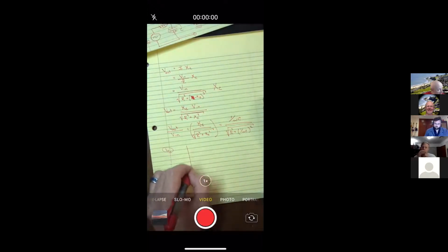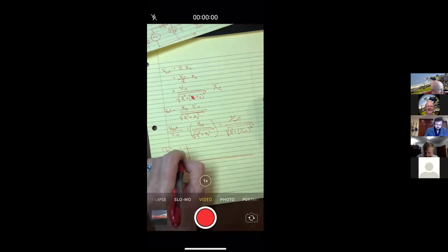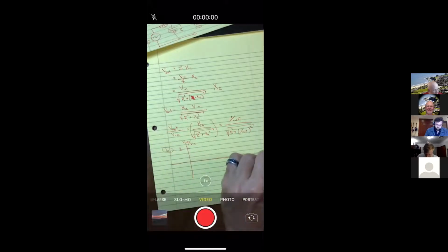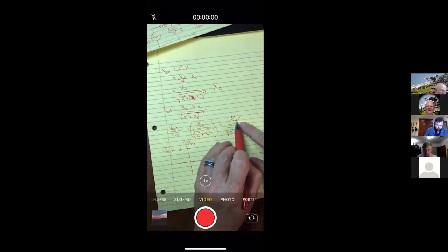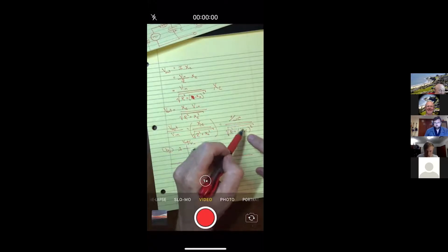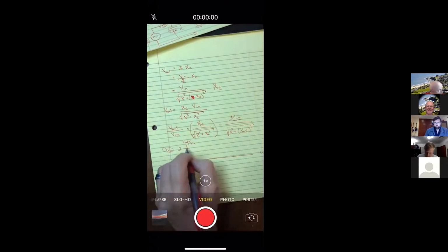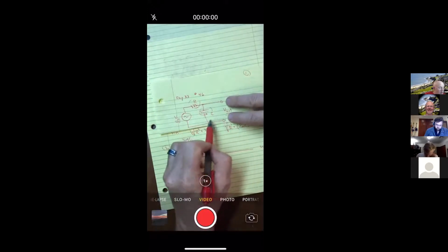So if I was making a plot here, and maybe I'll put the number 1 here, and on the vertical axis put the output voltage compared to the input for different frequencies. Watch what would happen at low frequencies. See, at low frequencies, this 1 over a small number is big, which makes this one big. So we can ignore that. And we essentially then have big over big, and they're the same big. So that's 1. So at low frequencies, we basically get the same voltage out that went in.